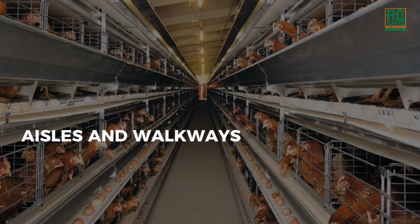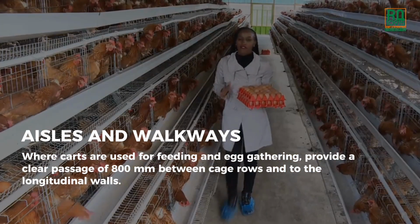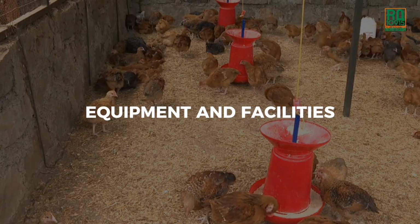Aisles and walkways. Where carts are used for feeding and egg gathering, provide a clear passage of 800 mm between cage rows and to the longitudinal walls. At the end walls, 2.4 meters clear passage shall be provided. Equipment and facilities.